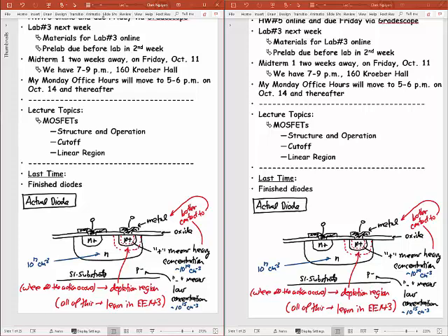This is obvious, but this will be the N and the P junction of the diode. So I'm really looking at a diode like this. From that point to that point, the diode looks like that, and it's planar in this case. When you look at it from a top view, what this looks like is this. When we're doing these semiconductor devices, the first thing you do is lay out everything on a computer program. You're drawing the top view of the structure. So in this case, this diode is going to look like this.